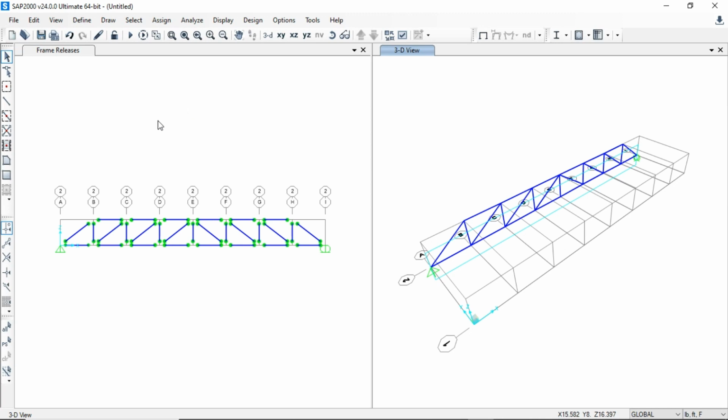So now we will replicate this truss. In the 3D view we have our truss on grid number 2 in the y direction. Here is our origin. We have moved 8 points from the origin, since the spacing between the y grid is 8 feet. If we want to replicate this truss on grid number 1, we have to move back -8 units with a minus sign.